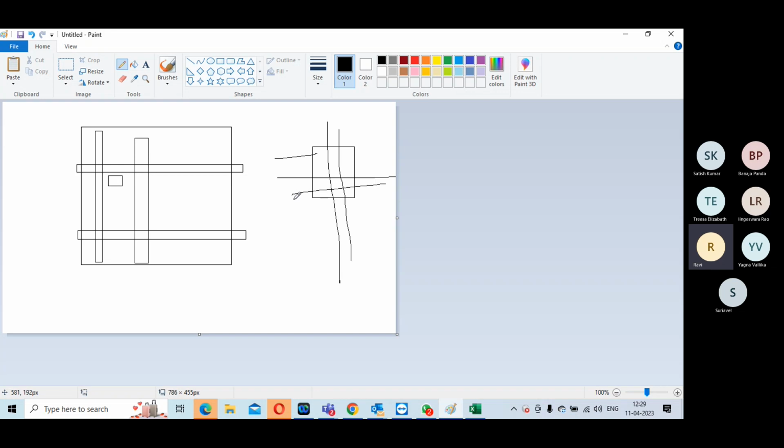Sleep or switch. There are three signals, and we will talk about that: input, output, sleep signal. Based on which it will decide whether power has to come. So this is the net, the mesh to which this mesh is supposed to get connected. You'll have to add as many as needed, because the drive of each power gater is very small. It may be 10 microamp or 10 milliamp or something like that.